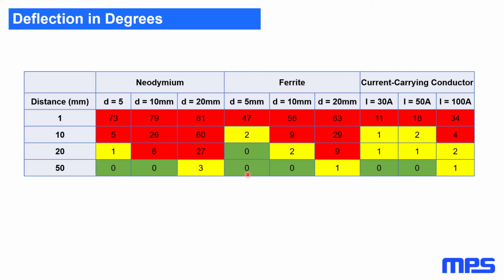One thing I will say, by the way, for our position sensors, even the position sensors that are non-differential, you can at least tell when that interference field is coming in. We have mag high and mag low. These are essentially diagnostic registers and diagnostic outputs on our sensors. And so if you were to get something like this, where you've got this large deflection, the sensor would at least tell you, hey, something's not right. I'm seeing more field here than I expect to see in the real application. Don't trust the output. So you at least get that, but we want to be able to trust the output.